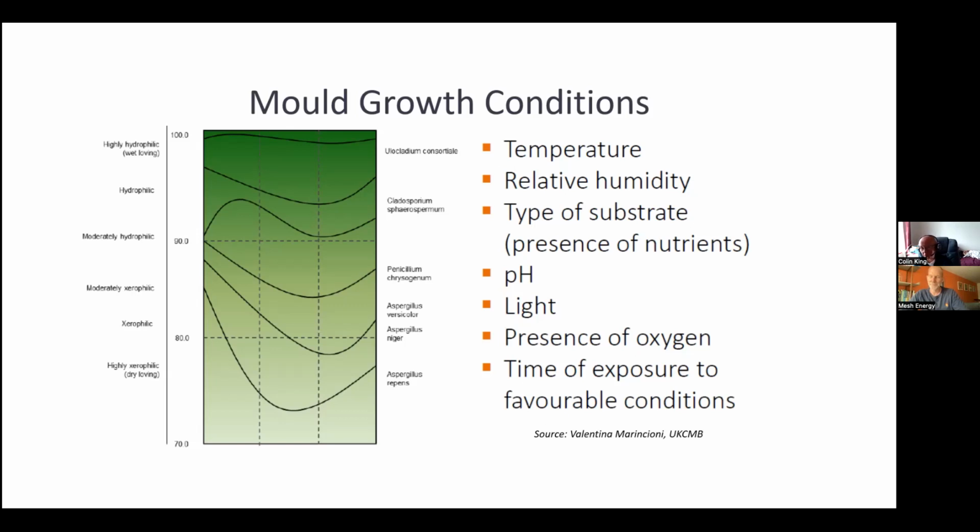They can work. I've actually used them. I've used Storm Dry, which is a brick cream, and I used it on a listed building. So yes, they do, and they act a bit like Gore-Tex for buildings. The issue with them really is, how do you ensure that the application is homogeneous, that everything is covered?